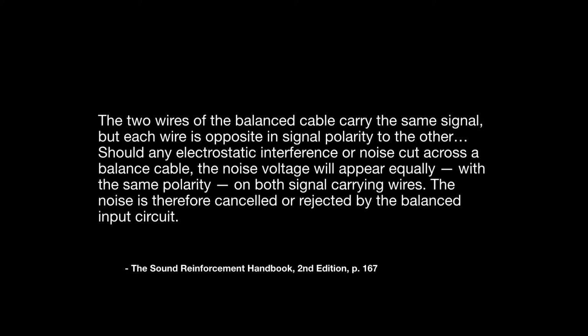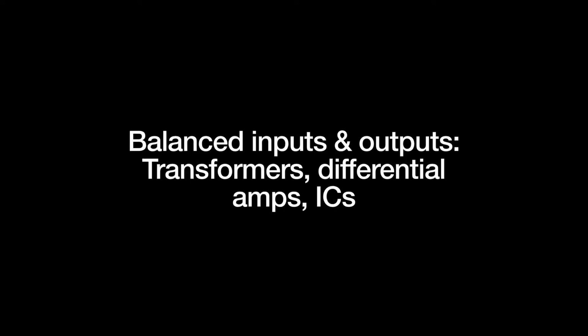So just a quick run through of how that works. Now, achieving a balanced signal from different pieces of gear can be done inside of the gear in a variety of different ways. It can use transformers, and we talked about transformers a few weeks ago. It can use what are called differential amps, and it can also use integrated circuits. And each of them have their kind of benefits and costs, if you will. I think generally a lot of people assume that transformers are going to change the sound a bit more than perhaps an integrated circuit will.